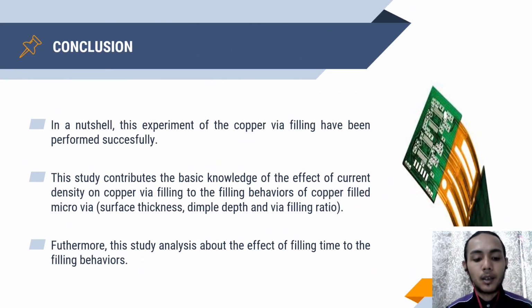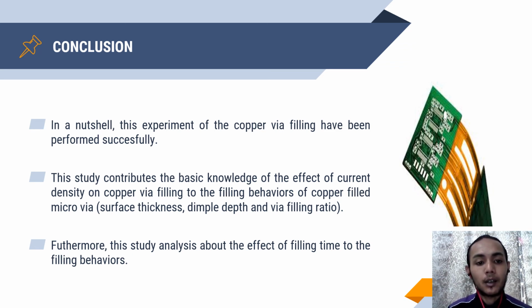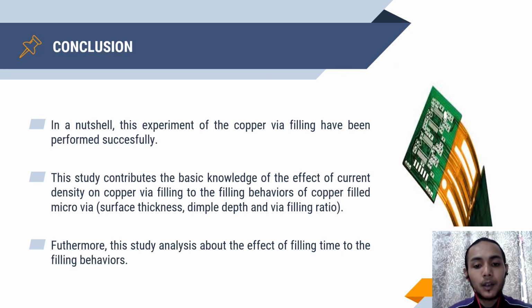Okay, as a conclusion, this study describes a copper electroplating enabling technology for filling microvia. In a nutshell, this experiment of copper via filling has been performed successfully. The study also contributes basic knowledge of the current density effect on copper via filling and the filling behavior of copper filled microvia. Furthermore, this study analyzes the effect of filling time on the filling behavior.